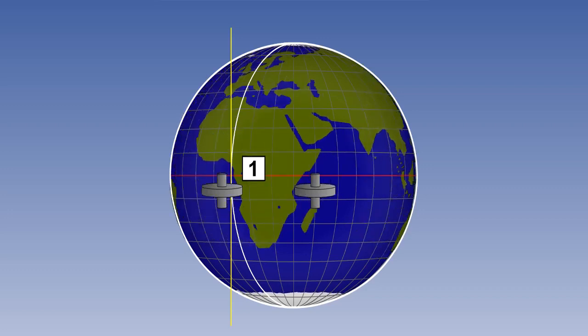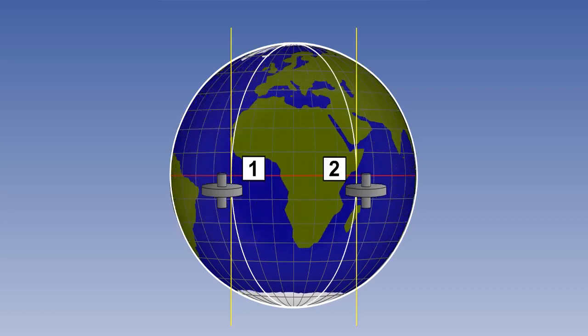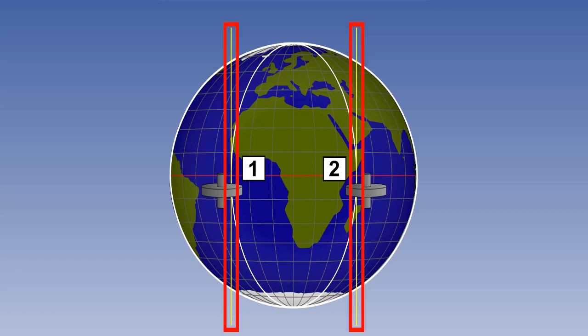As the Earth rotates from position 1 to position 2, the gyro axis remains fixed in space and also remains aligned with the local meridian. At the equator, the gyro direction has not changed with respect to Earth direction. It is still pointing in a direction parallel to the original one, which is true north. Earth rate is therefore 0.